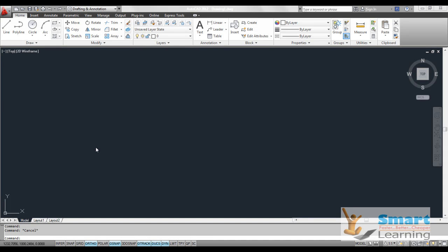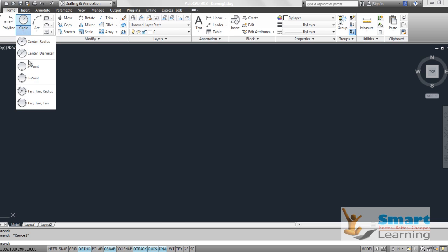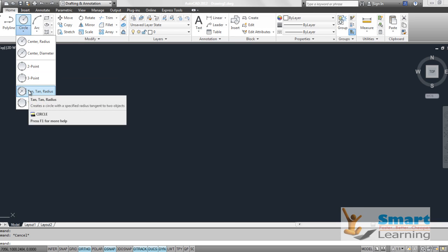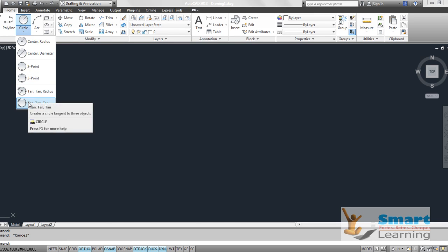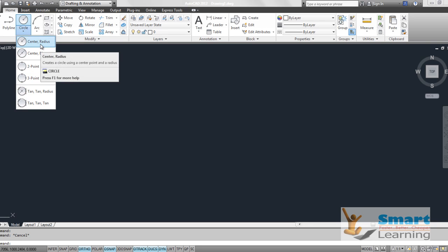In this video lecture, we are going to discuss the different options available inside the circle command. If you look at the circle command, there is a separate option below it. If you click that, you can see the different options available inside the circle command: center radius, center diameter, 2 point, 3 point, tangent tangent radius, and 3 tangent. We will go through them one by one.